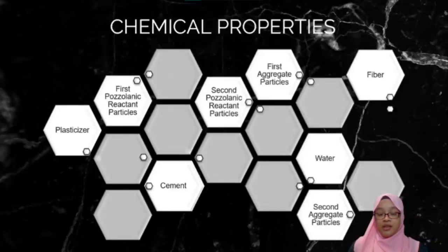Next is second aggregate particle. It can be made from silica sand, pulverized silica containing powder, volcanic ash, rock powder, or other material. The mixed proportion gives a smooth grading curve and satisfies the upper limit of the grading distribution in a case where D75 grading is about 50 micrometer and D50 grading is about 10 micrometer.